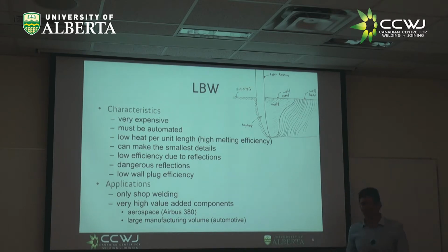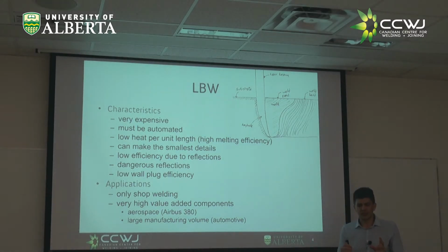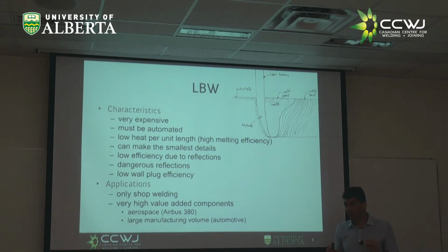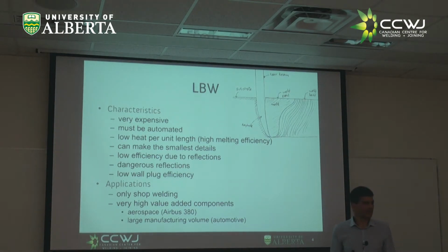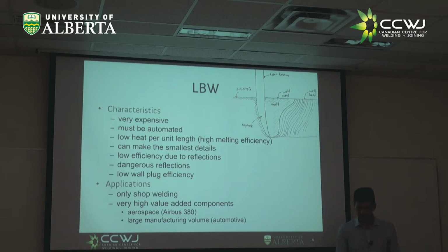Another characteristic of laser is, although it's very intense, so hot enough to evaporate, it is so localized that in the end, how many joules per meter you put are low, right? That's what we call the heat input, right? The heat input in laser is typically low, right? And it's a paradox. You say, oh, I have this super powerful machine that gives me low heat input, right?